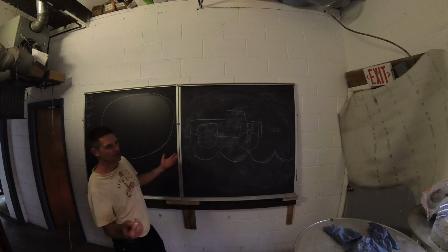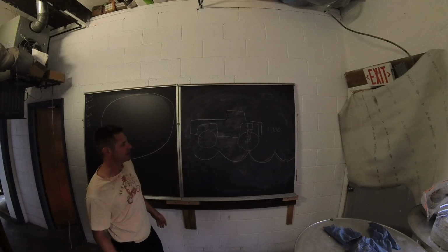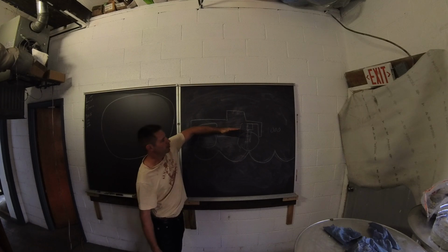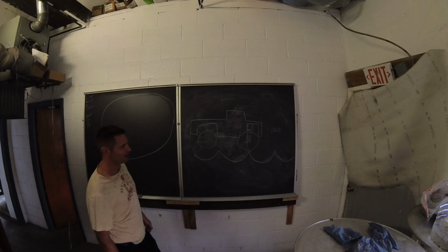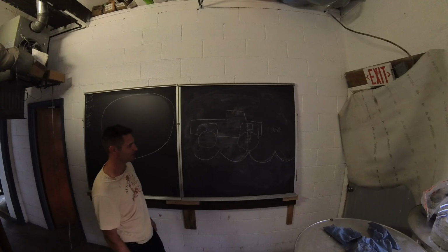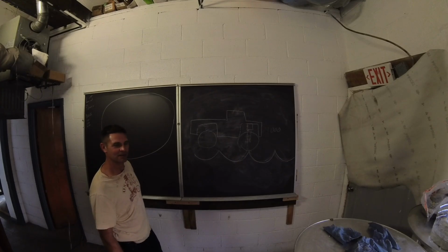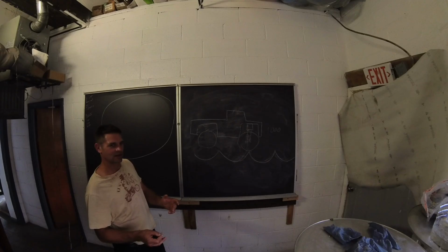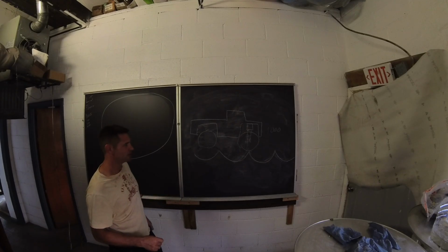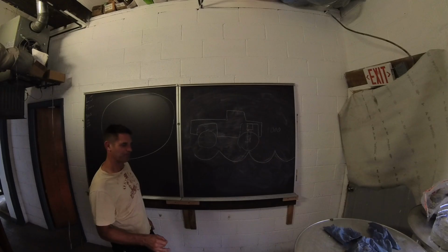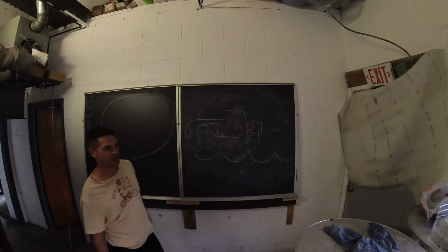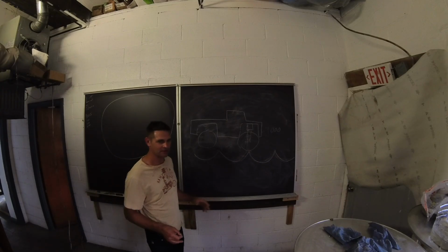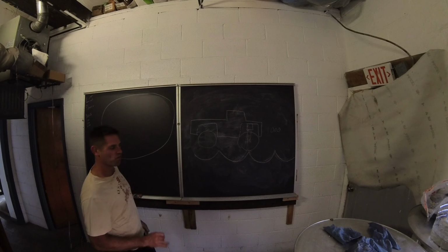Not realistic, no, but it's to get the point across that the ultimate suspension system doesn't necessarily have damping. If you can have the right amount of force at the right time and change that force, you don't need damping. Like I say, damping is a band-aid, kind of. And the more you get into suspension dynamics, things get interesting.